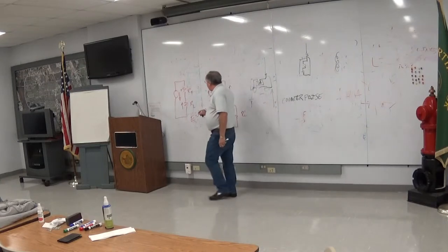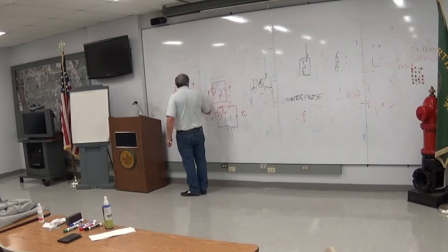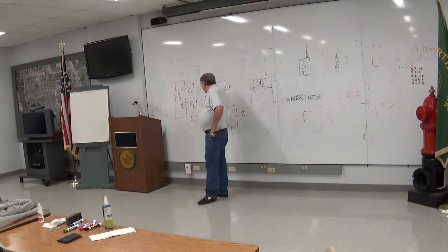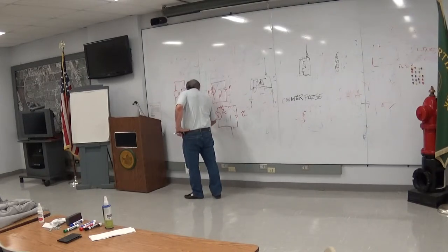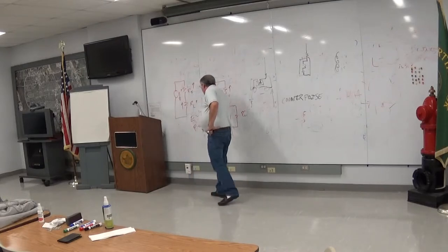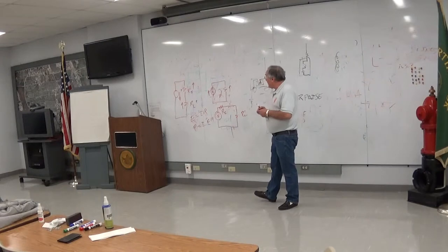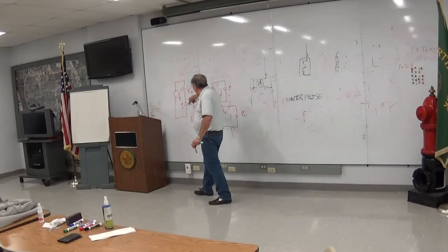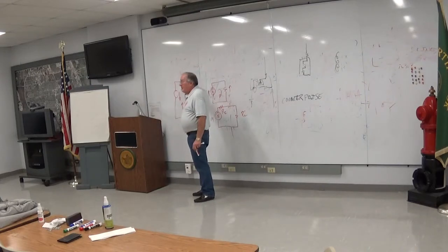Okay, well, what if this were big and this were small? Same problem in reverse. Now all your power, which is the product of that current and that voltage, is going to be affected because when you bring the resistance up, you're going to bring the current down. That's not good. And if you bring the resistance of one part of the circuit up relative to the other, it's going to see the voltage drop at the same current. Remember, they're in series, so they both have the same current, which means he's going to get more of the power than the other.